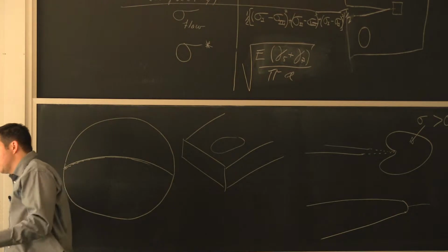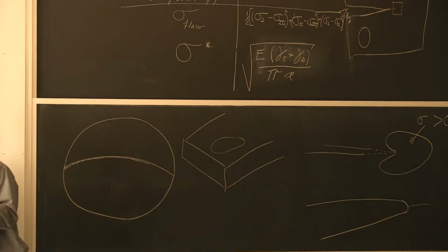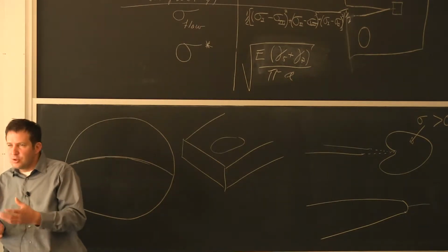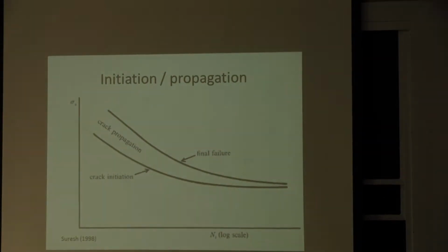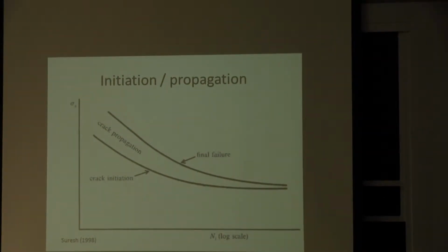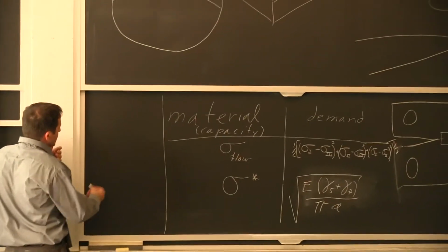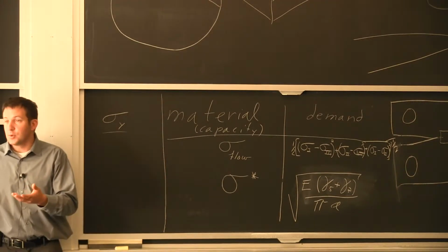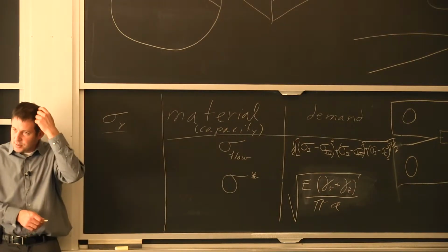Essentially, you can think of the endurance limit as a condition where the stress near all the little impurities in the steel are still at a level that doesn't create too much plasticity locally. Because what happens, if you think of the material, that's probably a good way to address this. If you're looking at a material and say, well, I have a yield strain, and that's when I run my stress strain curve. You know you have impurities in it. So at the impurity, if you take it as a sphere, you have a stress riser of 3.